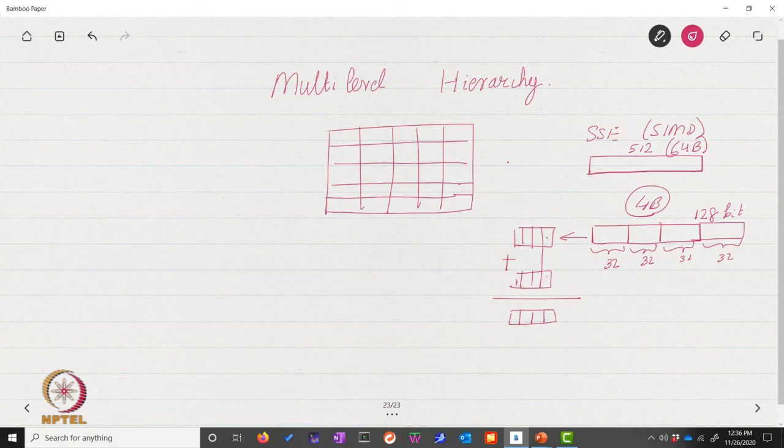So this is very good for all AI kind of algorithms, matrix multiplication and so on, in the sense that it is a kind of intra-instruction parallelism, where one add instruction adds 4 pairs of numbers in one go. This is also called SIMD, single instruction multiple data paradigm, and SIMD is heavily used in numerical computing. That is why most modern processors provide instruction sets for SIMD. Hence it is necessary to read large chunks of data in one go from the memory system.